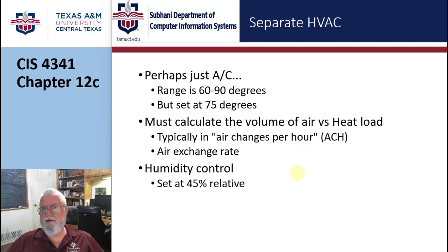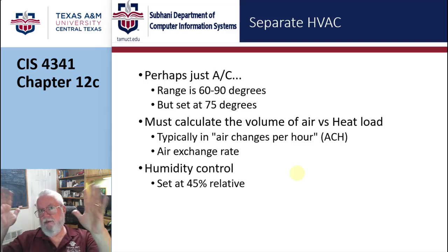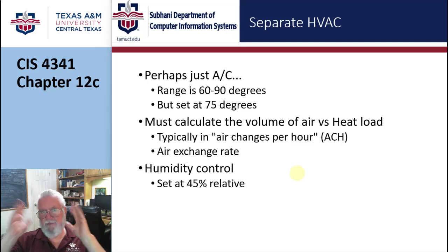So there's an awful lot of calculation. If you're going to an architect engineer firm and you're saying this is going to be a server room, their ears are going to perk up and they'll say, oh, that means separate air conditioning systems, separate ductwork, separate controls, separate air filters, everything is different. The rest of the building is just computers and humans, right? It's a typical office building. There's no manufacturing going on. It's just office space, but that server room is going to be different. And the humidity is kept right about 45% relative humidity. This basically prevents static issues.